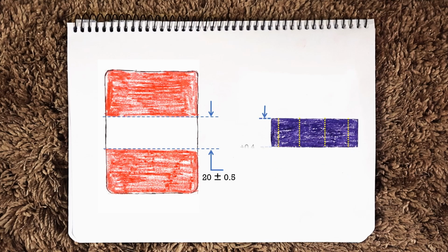And this is not a crime, because we haven't mentioned that the shaft should be straight or how much it should be straight. We have only defined the size, the diameter of the shaft with tolerance, and the diameter is maintained within its tolerance limit at every cross section.